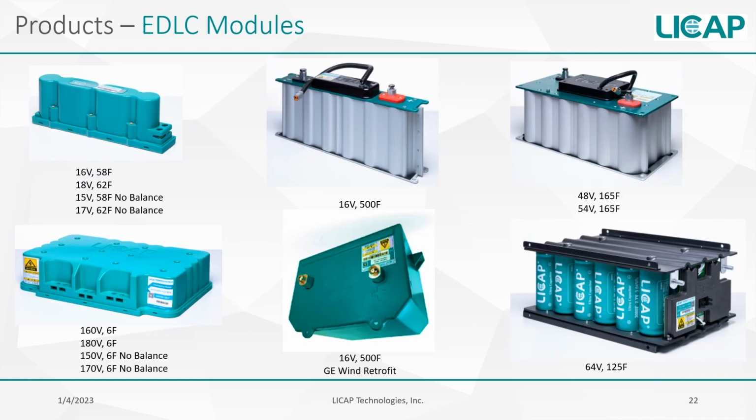Now let's talk about our module product family. In the upper left-hand corner, you can see 4 modules ranging from 16 volts to 18 volts using the same housing. These all use a variety of the different D-size cells that we showed on the previous slide. The 15 volt and 17 volt do not have any passive balancing resistors. That's why we have to derate the voltage some. Similarly, in the 160 to 180 volt modules below, we also have no balance options available.